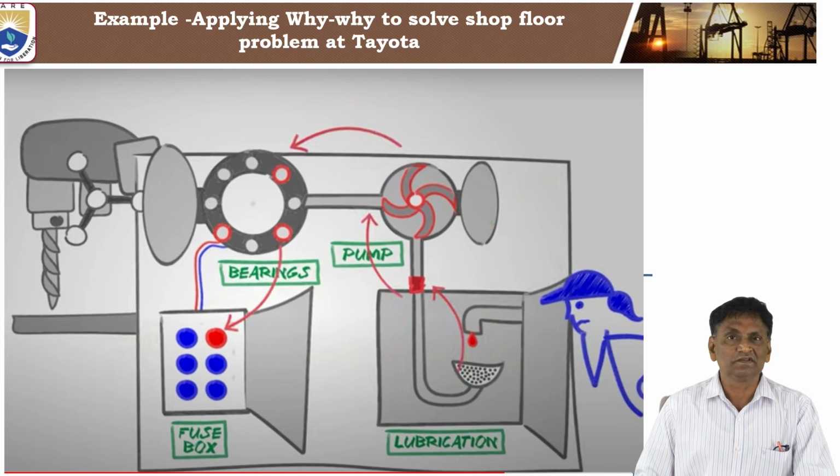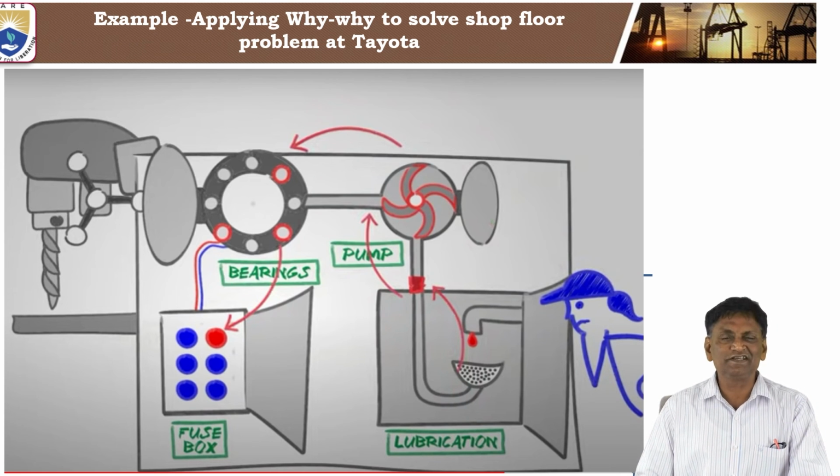So they concluded that the particular module is experiencing more current than what is designed for it. The motor is taking more current. Then the logical question is why the motor is taking more current. It was told that it is encountering a lot of resistance. Bearings are not smooth, so the motor is feeling resistance to motion.